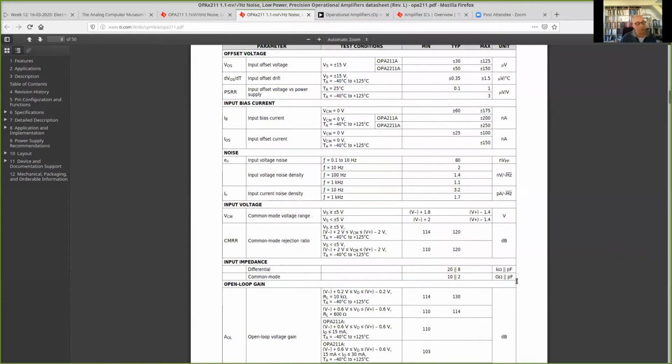Common mode, you see this is 10 giga ohm. Okay, I can put it in if you want, and then we have to put here a resistor of 20 giga ohm and here, because together they are then 10 giga ohm. But let's not worry about it. 10 giga ohm is so large that usually it plays no role in your circuit. And 2 pF, so I do 1 pF here and 1 pF there.